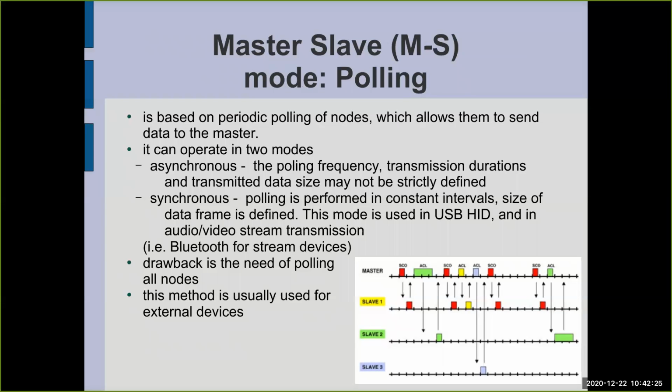So let's say for a mouse, it's okay. But if we have, for example, a security button, which protects us against some accidents, and we connect this button to the bus, and it is handled in polling mode, it may be very difficult to ensure high responsiveness.